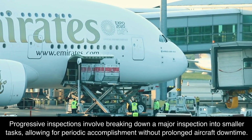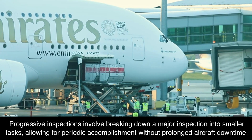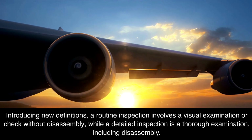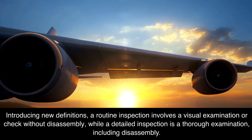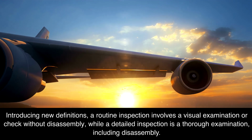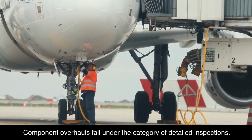Progressive inspections involve breaking down a major inspection into smaller tasks, allowing for periodic accomplishment without prolonged aircraft downtime. Introducing new definitions. A routine inspection involves a visual examination or check without disassembly, while a detailed inspection is a thorough examination, including disassembly. Component overhauls fall under the category of detailed inspections.